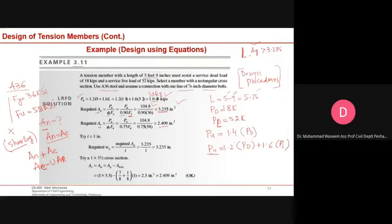Once you have the gross area, you have the bolts that are installed in this member, so you need to calculate the net area. If you are using the net area, eventually you have to calculate the effective area. So if you want to select this member as a tension member, then in this type of member you will have this shear lag. Why will we have shear lag in this type of member?